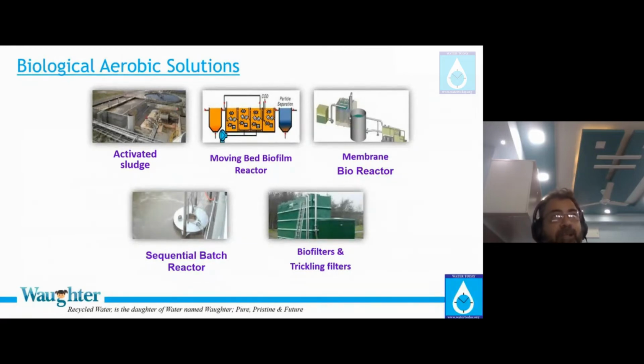One very big advantage of the trickling filter is that the air consumption is low, and the energy consumption per kilogram of COD removed is the lowest. Now, you can say, sir, when will I become the expert who can quickly do these kinds of calculations that you are doing? You are already the expert. You understand the fundamentals first, then design and engineering of each and every process is already done by two great scientists, Metcalf and Eddy.